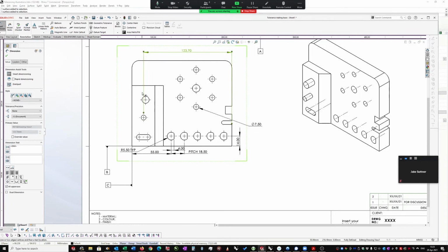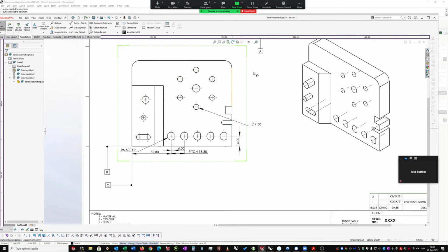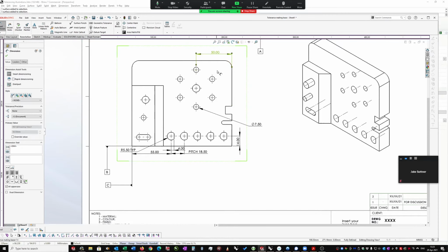This dimension line is crossing more pieces than it needs to. Actually, maybe not, but I think the principle will hold. So in other words, just as an example, if I were dimensioning that piece, put the dimension that side, don't put it this side where the dimension line is now crossing a whole lot of other features.